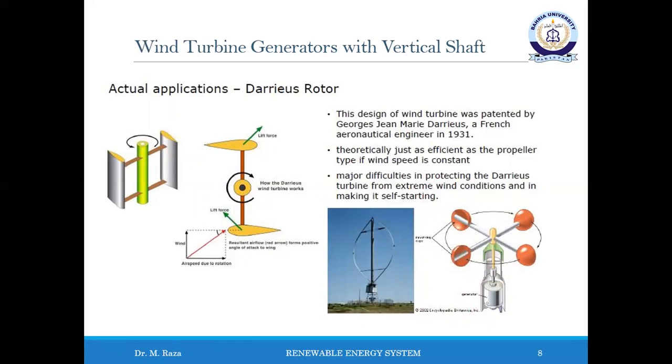The aerodynamic principles which rotate the rotor are equivalent to those in autogyros and normal helicopters in autorotation. As the aerofoil moves around the back of the apparatus, the angle of attack changes to the opposite sign, but the generated force is still diagonal in the direction of the rotation.